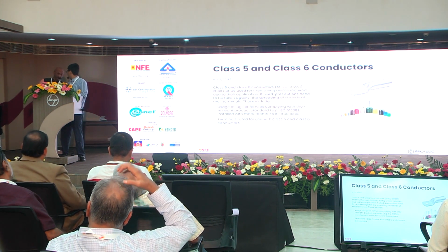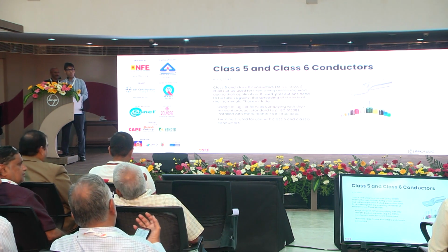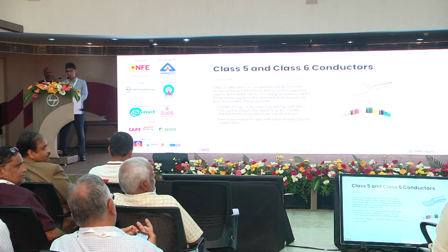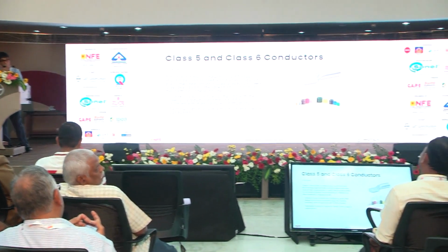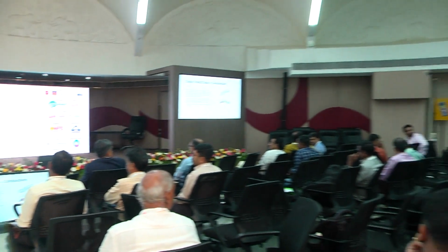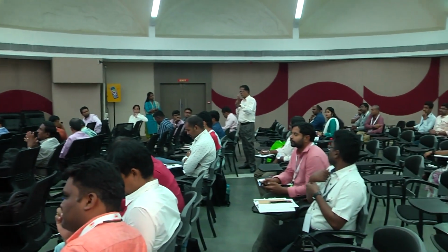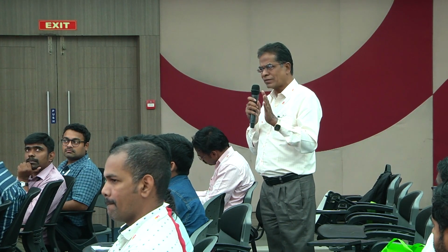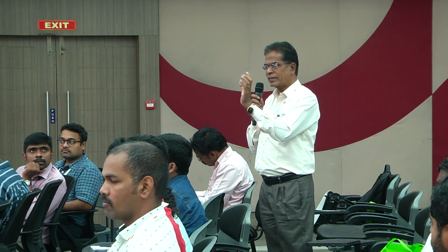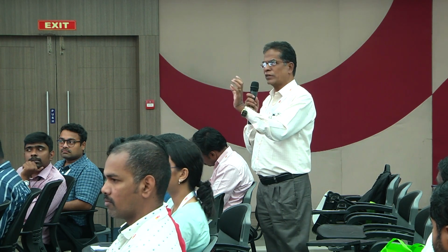I'm adding some more points on fire sealants. See, fire sealants are not only for cable bunches. It is also available as a current carrying conductor with the cable tray. Moreover, fire sealants are available for the external wall and the ceiling as well as the internal partition wall. There are 5 types of fire sealant products actually. Depending upon the intended use, we can use that product.